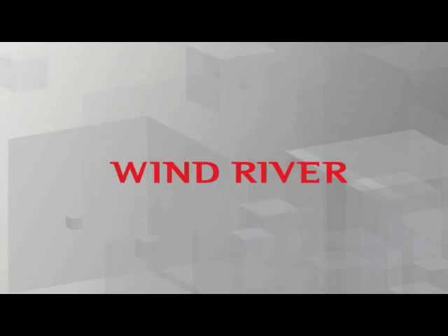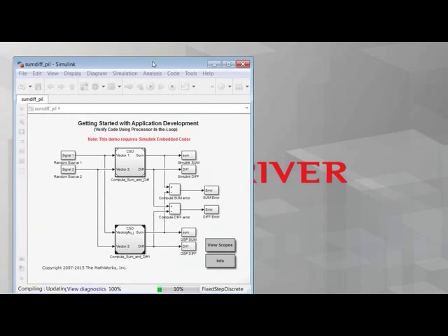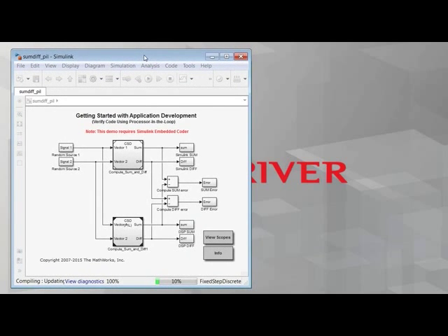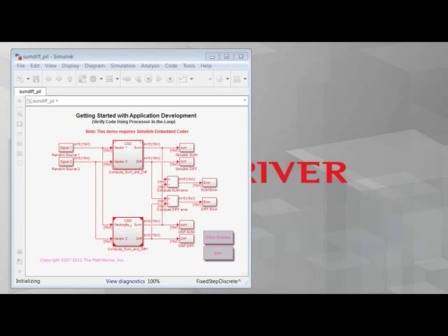Now in the first demo, I was working with a bare metal board. In other words, there was no operating system running on it, just our controller code. Simulink and Simics work together directly to facilitate the controller to plant model communications. Here I'm going to run a script to do what we just did, but with the VxWorks operating system. I'm also using a different model.